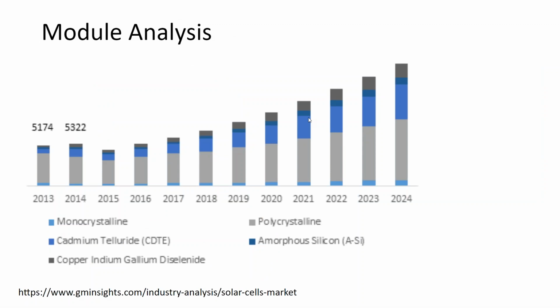As far as the module technologies go, you pretty much want to do monosilicon, and polysilicon is fine too, often a little bit cheaper. Overseas they might be using less efficient panels that are a little bit cheaper. There's nothing wrong with that. In fact, it's a great strategy. In the US, by the time you're paying all these soft costs, you might as well spend a little bit more and get slightly better than the global solar panel. And so most solar projects in the US are installed with monosilicon. It's considered to be the best. It has really good market share. And polycrystalline is more similar to monocrystalline. It's still silicon. They make sheets of it rather than cylinders of it.